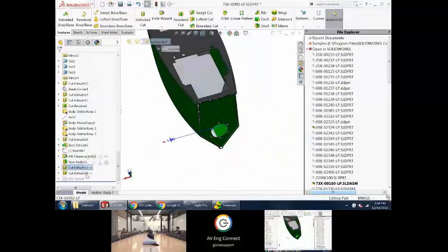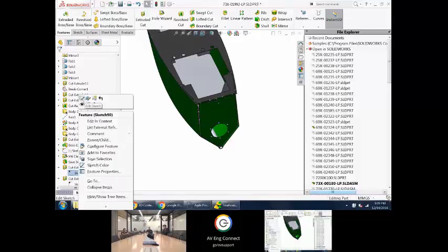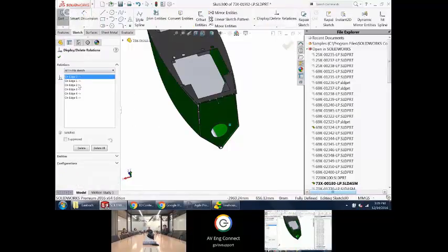Okay, but I've got these blasted external references. I showed you a quick and dirty way. Just right click, break them. You're done. It's not going to look at them again. A much cleaner way of doing it, so you actually don't have any trace of it, because remember when you break it, you just get a big X next to your external reference. But if I go into this sketch, go to display delete relations, set it to external, and kill them all, there went all my external relations.